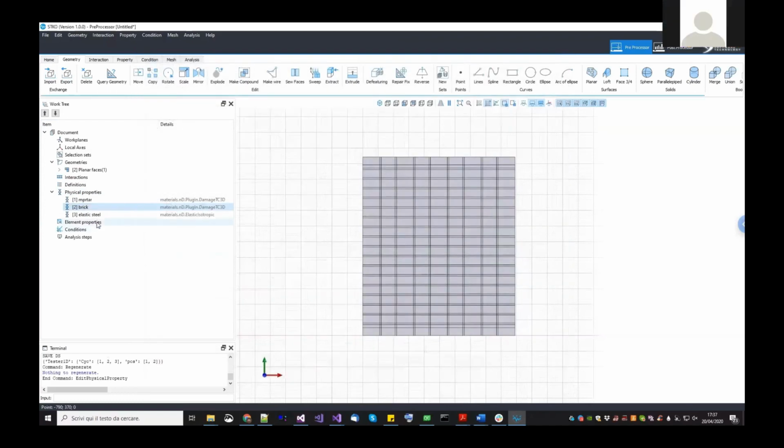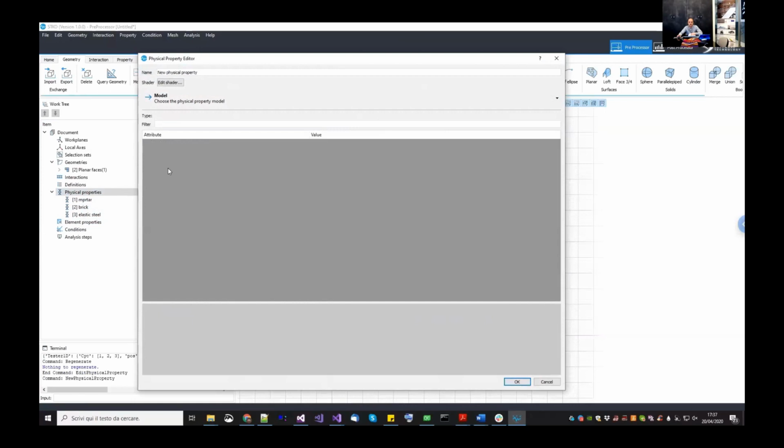Okay, this is fine. So as I told you, these are 3-dimensional models. Now we are going to convert them into plane stress models. In the shell, we used the plate fiber because the shell has a thick shell formulation, so we need the out-of-plane shear, but we don't have the out-of-plane stress, the direct component, so the sigma ZZ. Now, in this case, we need to use the plane stress. So both the out-of-plane stress and the out-of-plane shear should be 0. So we need to convert all of those elements to plane stress.